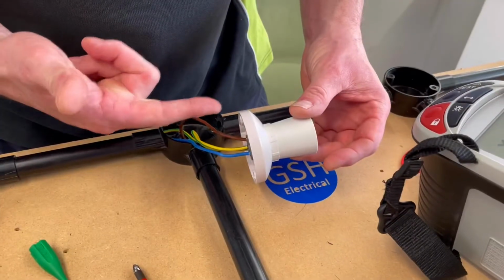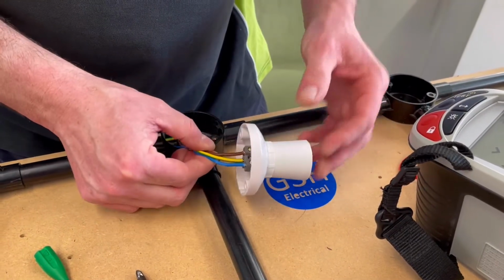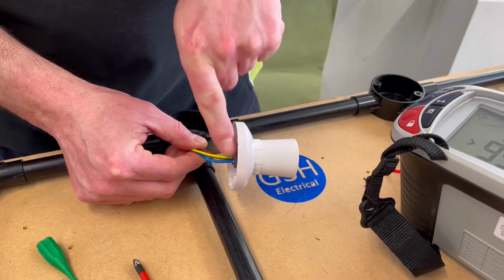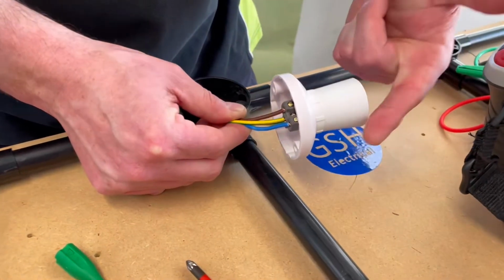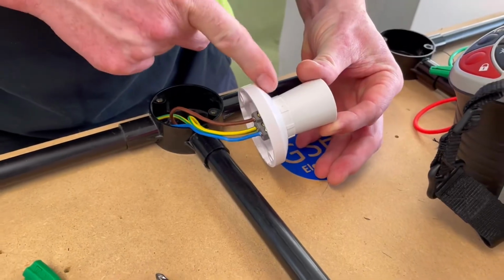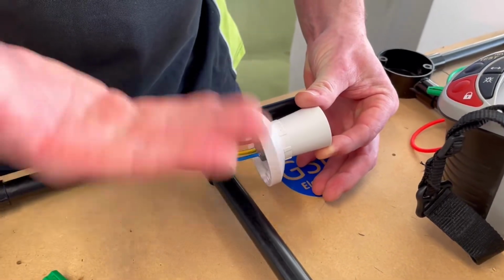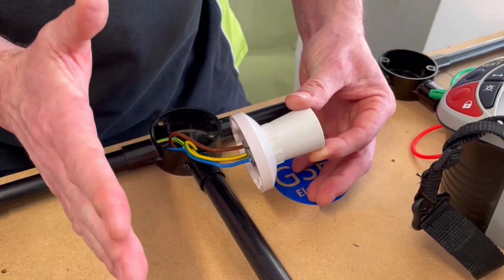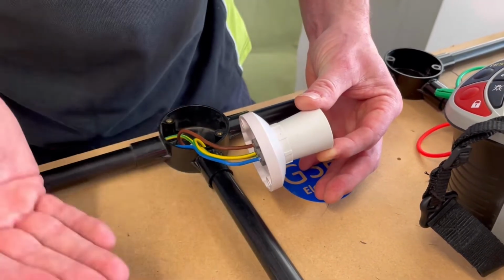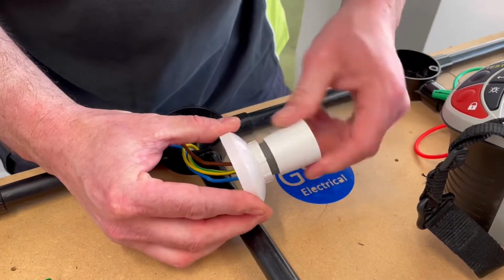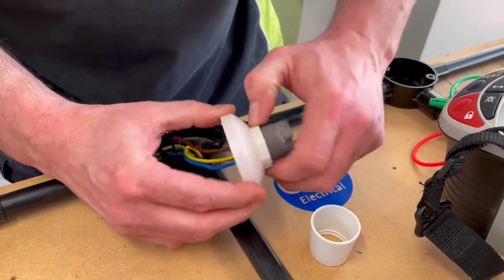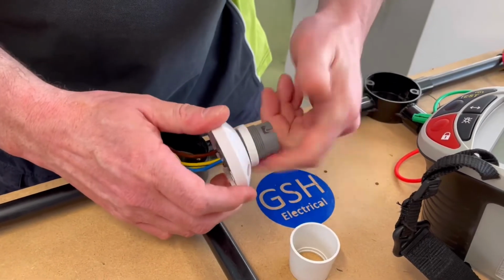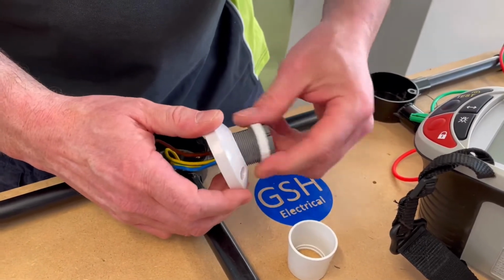We said in a previous video that this straight skirted batten lamp holder would better be unassembled in order to probe on to do the test, because it becomes quite tricky to make those. However, at the end of the lesson, I said to people to rebuild this because you didn't want to lose the parts. So I've come back, I've had a break in a session, and I'm now going to test for this continuity of CPC, including the polarity test. I'm going to unassemble my straight skirted batten lamp holder to make it a lot easier for me to get onto the actual terminations for the connections for the test.